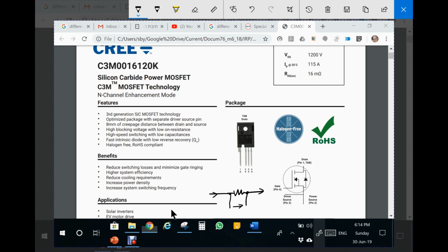So in this case, if there is a connection here and a connection here, these wires actually reflect the actual voltage on this resistance. So this is the basic idea of the Kelvin connection after Lord Kelvin. And in fact, there is a Kelvin bridge for measuring resistances very accurately by this trick.